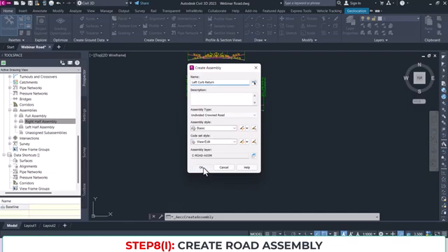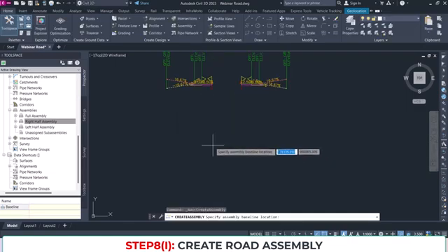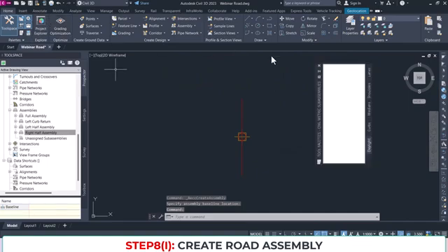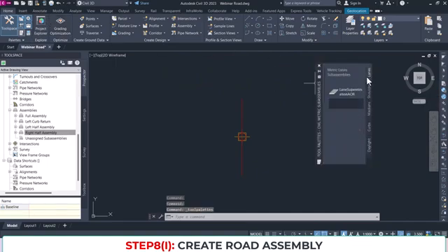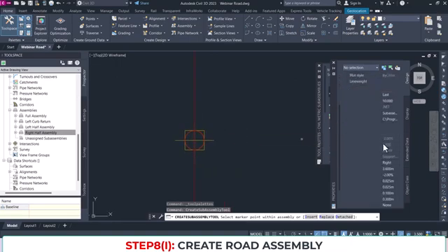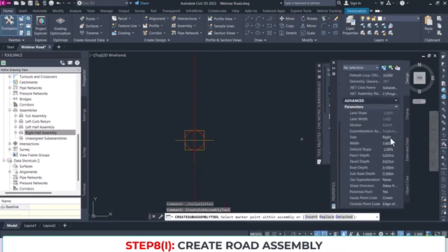Everything remains the same, and then I'll click on it. It zooms in for me. So I open my tool palettes again, and then I go to lanes and then model lanes per elevation. Now this time, as I'm walking to the right, I'm actually walking towards the left, because you'll see that in a moment. So I'm walking to the right, and my lane is 3.65 meters.